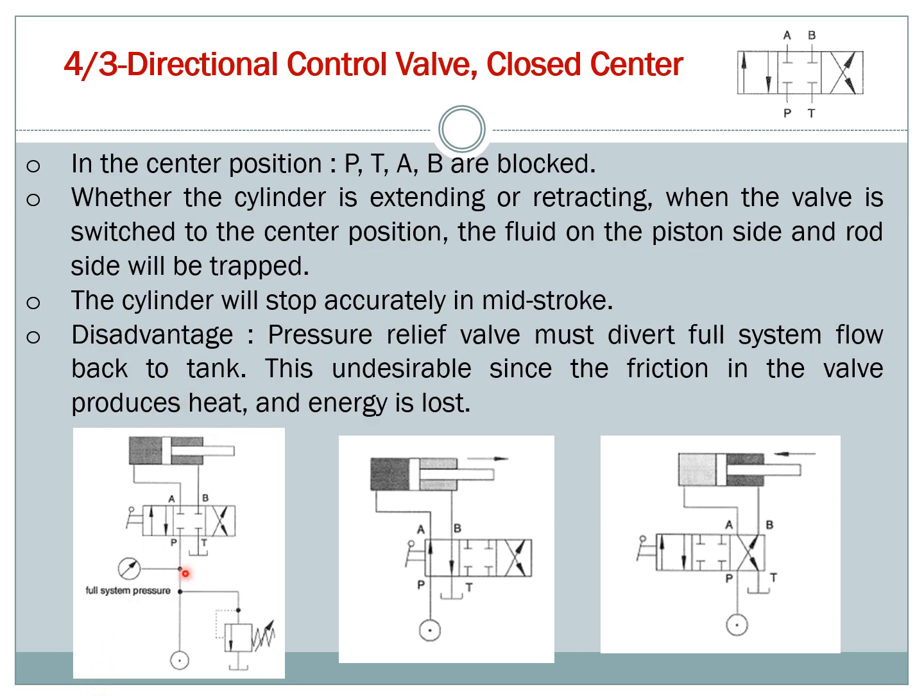Okay, so these are some ways of adjusting the system. You can see it's in the middle. When you move the hand lever, your cylinder will extend. And when it's connected to the right hand side, your cylinder will retract.